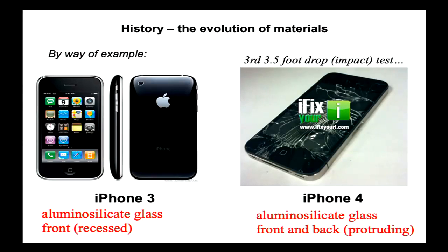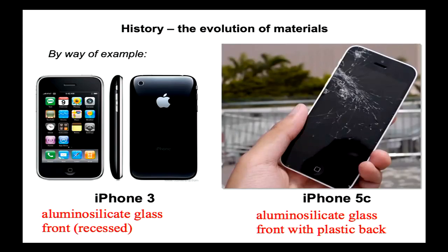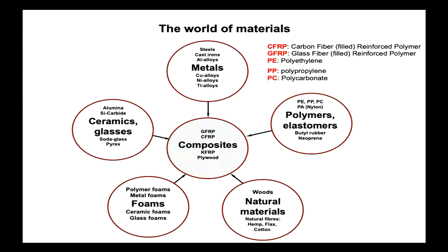Dropping the phone in just the wrong way would result in the glass clipping the ground first, and that impact load would be enough to cause the shattering. It wasn't long before Apple put, I'm sure it's a polymer of some form, around the edge, just like a bumper bar, a safety bumper. So that bit of rubbery plastic absorbs some of the impact load before the glass comes into contact. So, materials.